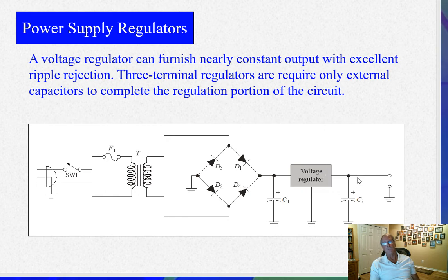So they'll only supply a certain amount of power. They're not limitless. But there's a lot of different kinds of voltage regulators, and we get into that in integrated circuits in the spring. These 3-terminal voltage regulators also have 2 capacitors. This is one of the filter capacitors that we were talking about before. It also has this capacitor on the output, and typically that's used to handle load transients.